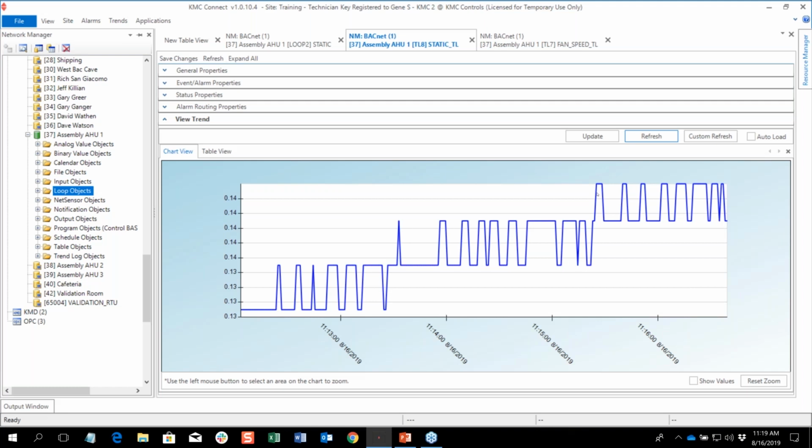One thing to remember about anytime we're using integral, that integral can add or subtract from the loop value to drive out that steady state error. So if I put bias in to force it to 0.18, that integral maybe would unwind and eventually bring that bias out. So for any loops that I tune or that I would be involved with, I don't generally use biasing anytime that I use integral. Biasing, for me, is really reserved for proportional only type of actions and systems.